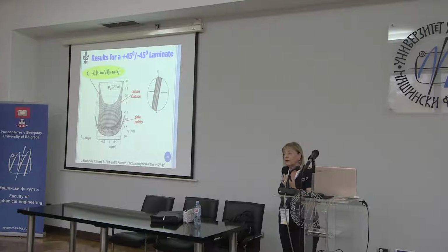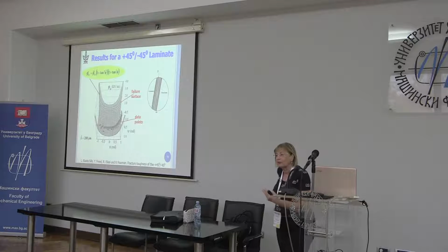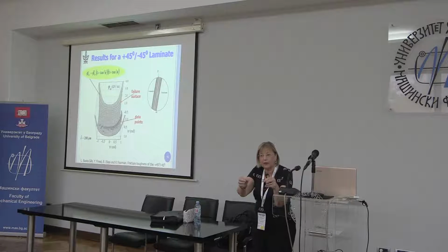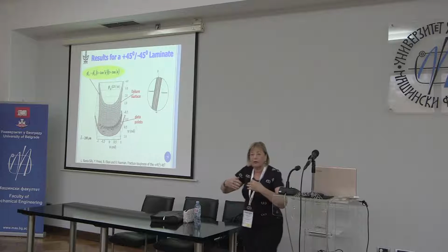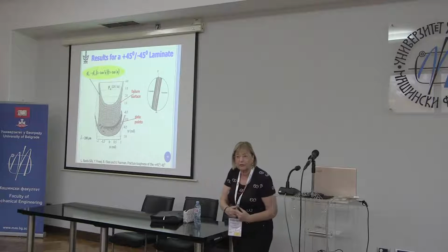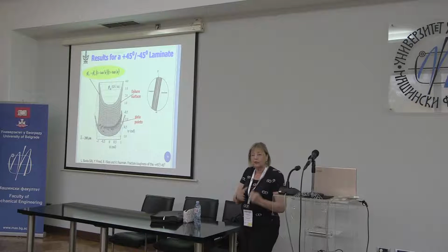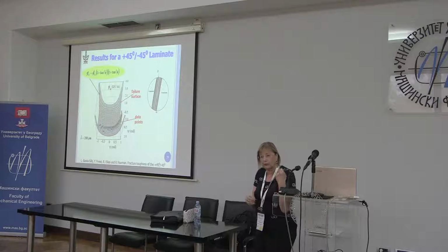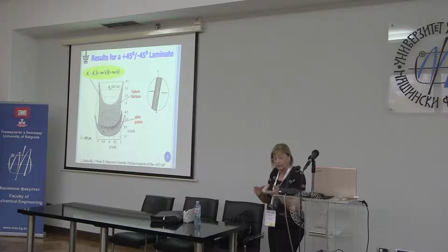In fact, my thesis advisor says you always have to tell a story. So the story was that some of the points along the delamination front reached failure, so they're going to start to propagate. The others that didn't reach failure are going to be dragged along by the momentum of the rest of the delamination propagating. So we only really had a problem with 2 specimens where all the failure points were below. We're in the safe zones.